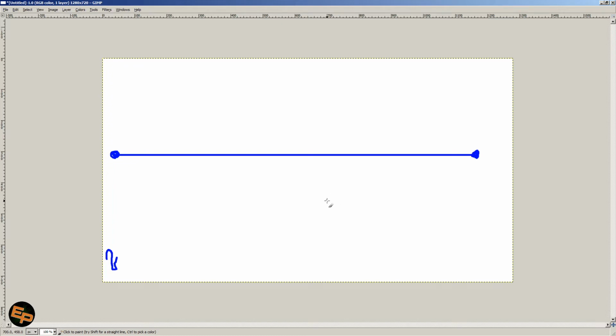So you need to do something to have this wire, let's say that this is a wire, pass through the center of a toroidal core. And of course this means that you will need to break this wire, or desolder it, or disconnect it, however you can, in order to insert it through that toroidal core.